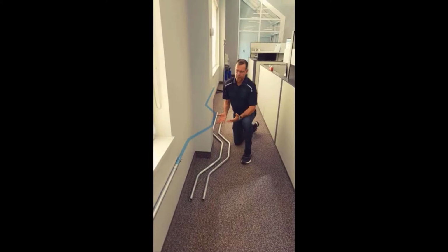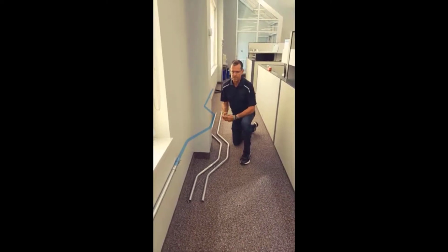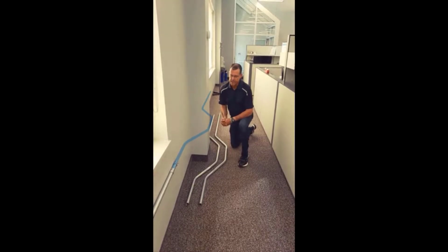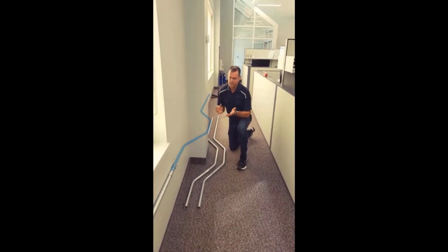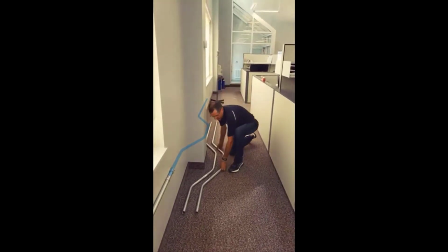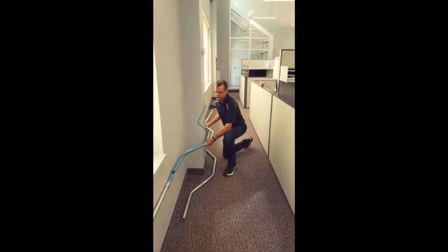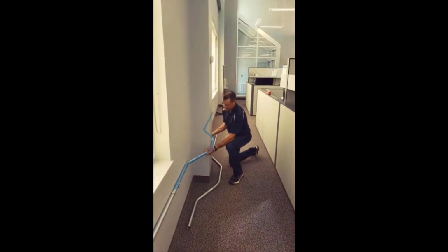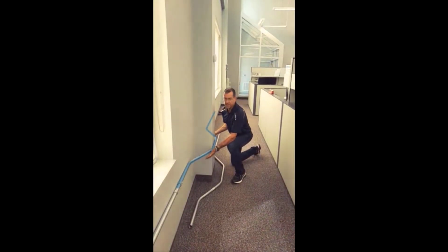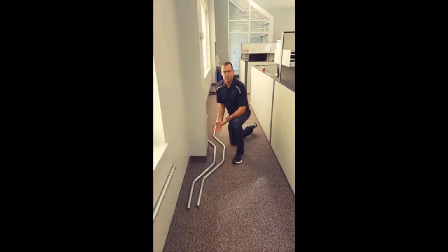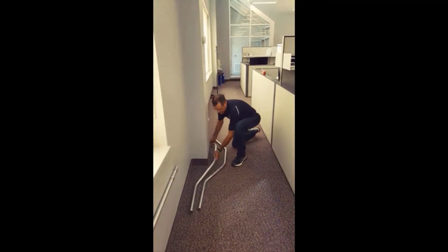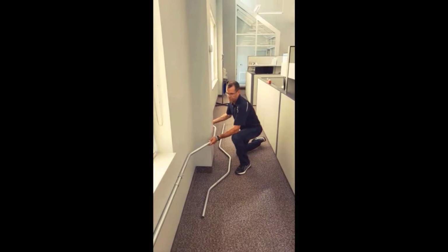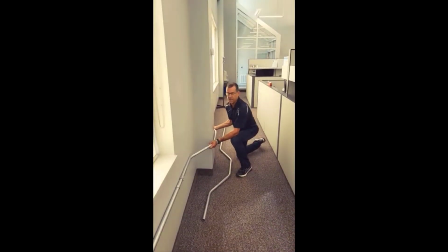Okay, we're back over here, ready to install our 4-point saddle. I'm going to do the machine bend one first and then the manual bend after that. But to show you how well this fits, it should fit. Okay, so we're going to shove that into the coupling. Look at that, no math, and it fits like a glove. And now I'm going to show you the manual bent one. Again, I just threw the marks on there coming off the spool sheet. I'm going to shove it home in the coupling. It fits like a glove.